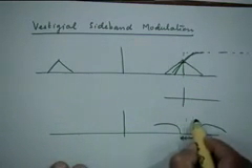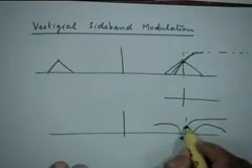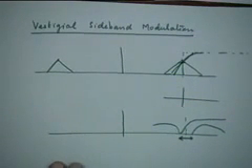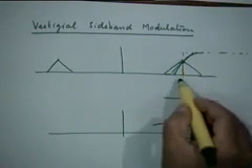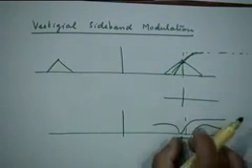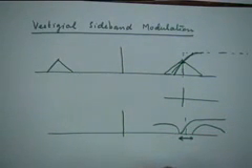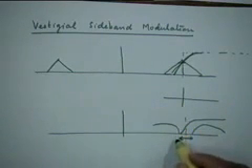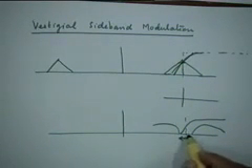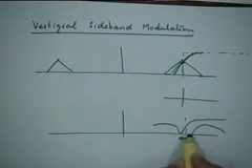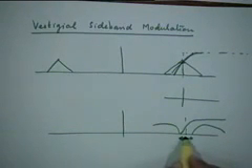And that gives me flexibility in designing this filter. The filter design can be done. I don't need a really sharp cutoff filter, in the sense of a brick wall characteristic. There is a band available over which I can gradually roll off the characteristics of the cutoff filter, the sideband filter, which is not going to be available to me if this band was not available to me. You appreciate this point? So in certain kinds of signals, and also there is a second point.